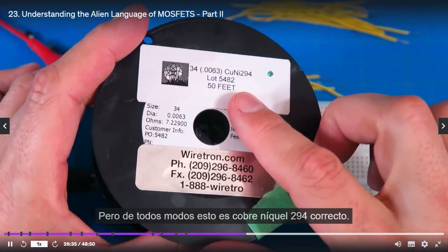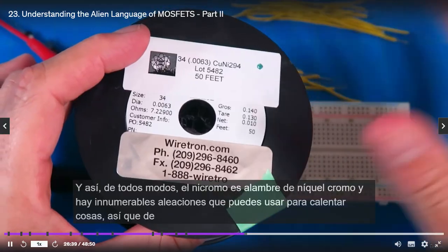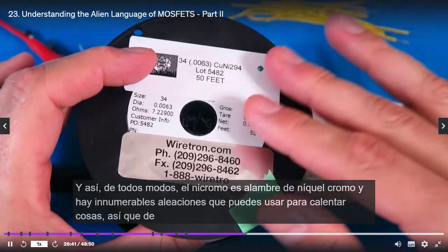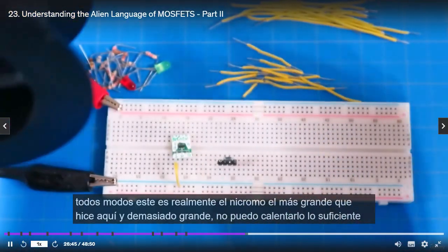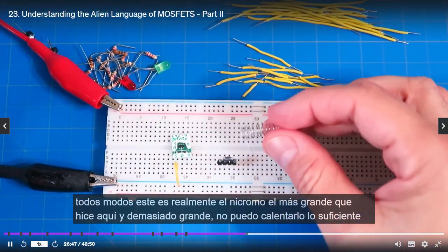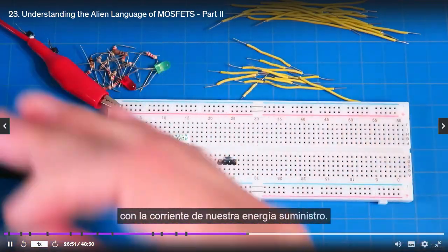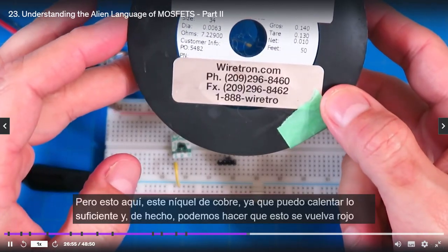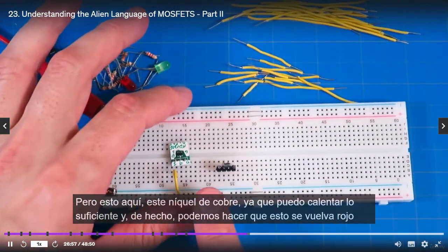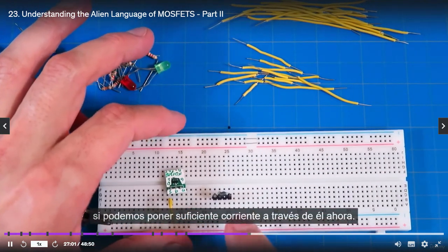But anyway, this is copper nickel 294, right? And nichrome is a nickel chromium wire, and there's countless alloys that you can use for heating things. So this is actually nichrome, the big, thicker one here that I made. It's just too big, I can't heat it up enough with the current from our power supply. But this right here, this copper nickel 294, I can heat up enough, and we can actually get this to turn red if we can put enough current through it.